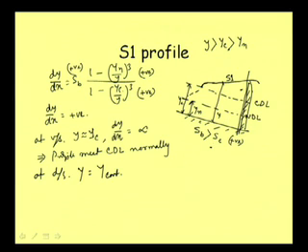But here the flow has somehow gone up above the critical depth line. So, when it is flowing here, it is a subcritical flow, and this control section will just govern what the depth of flow at the downstream point should be. That we will discuss in more detail later. But this downstream y is equal to y of the control section.